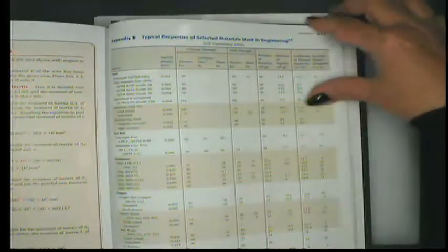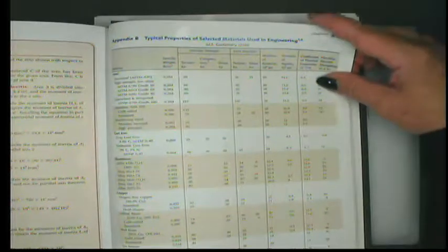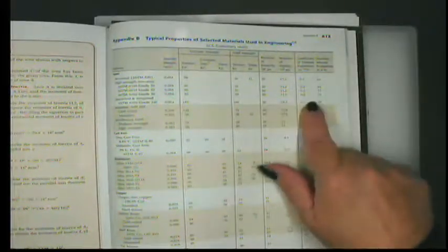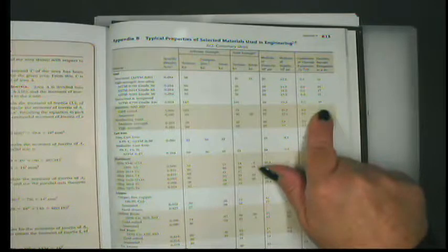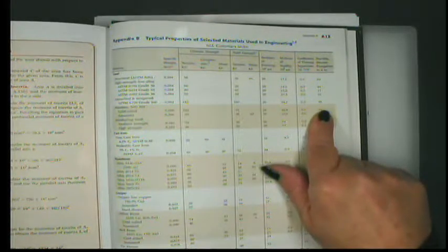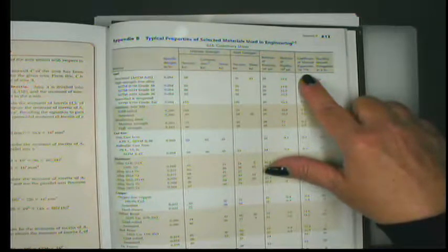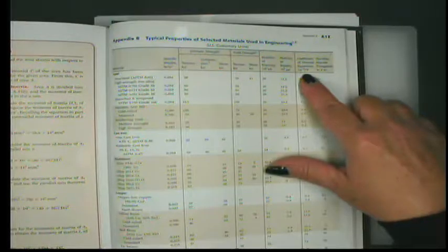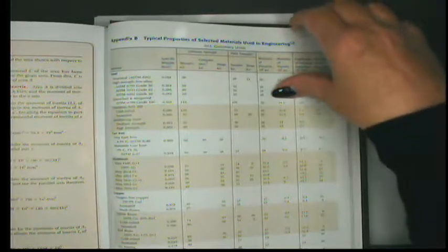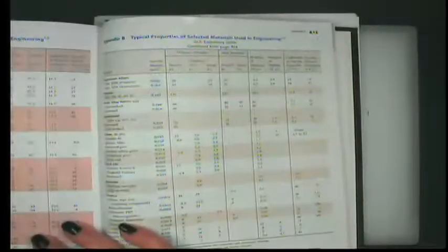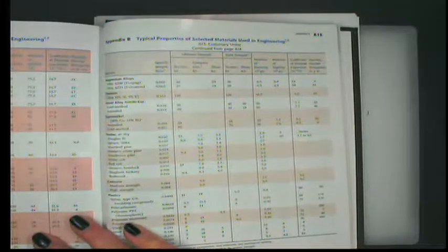We'll talk a little bit about modulus of rigidity later on, but that's related in a way. And then we have some other property, the coefficient of thermal expansion. Remember we talked about sidewalks, the expansion cracks in sidewalks and so forth, how materials will expand with temperature. This is a very small number, 10 to the minus 6 per degree Fahrenheit, which makes sense, because you wouldn't expect concrete to double its size if you increase the temperature by 100 degrees. It just increases a little bit, but it's still enough to mess up your sidewalks.